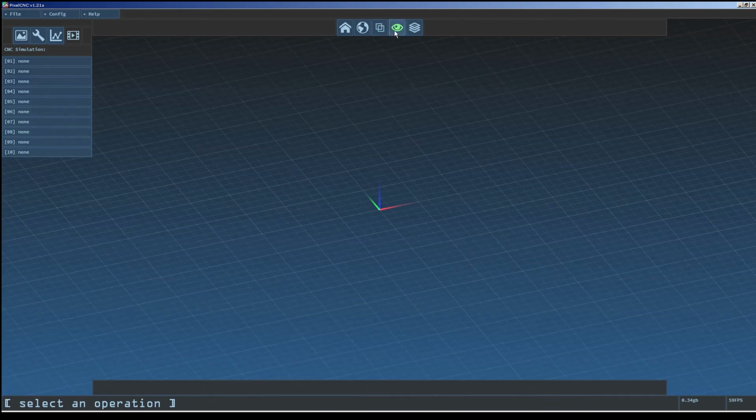The I button is used to toggle the visibility of any toolpaths in the 3D view, regardless of the active mode. This is useful when toolpaths consist of numerous cuts and rapids, which can obstruct visibility of simulations and make it difficult to discern the quality of a cut. The Stack of Squares button toggles whether or not rendered toolpaths are obstructed by mesh geometry in the 3D view. This can be thought of as toggling whether toolpaths will appear through a mesh, as though it were transparent, or see-through. We will use these different buttons as they become useful over the course of this video.